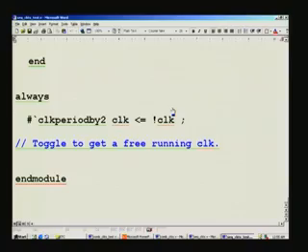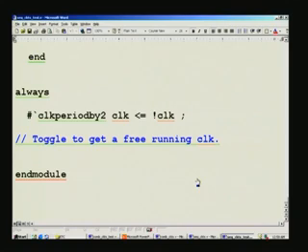With this, I complete the test bench, and if you have any questions, I will be happy to answer right now, or offline you can ask. Can you elaborate on that last module, the clock module? Which one? This clock. So, we started with clock equal to 0, right, and what is 0? If you invert, you will get 1. So, this will happen every 10 nanosecond, because this is 10. So, always with a delay means that always after 10 nanosecond do this. So, 0 will be 1, 1 will be 0, and for eternity it will go on till power fails, right.